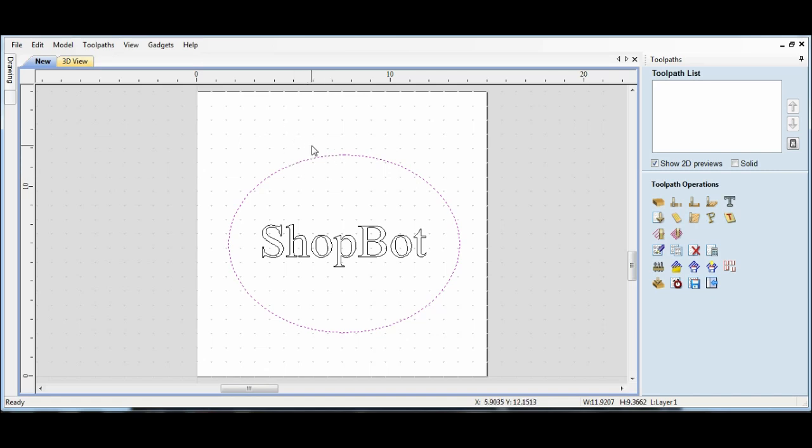And once again, once we go on the machine, I'm just going to be cutting this piece out, using a 1/4 inch bit. I'm going to go down a couple times. Since I just have 1/2 inch material, I'm going to do it in 2 passes. First pass is going to plunge 1/4 inch down into it, and then move around the object. And once it gets to the top again, it's going to plunge all the way down through it, and then do 1 more pass.